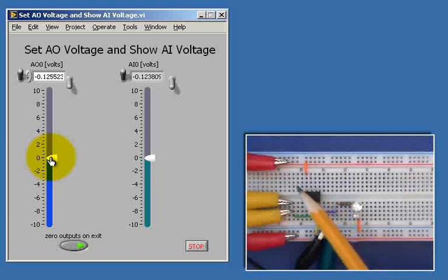So I have the voltage follower circuit implemented here. We use the ±15 volts for myDAQ. This is the same collection of signals we were looking at earlier. And then I take the voltage follower output and use that to operate the heavy load.